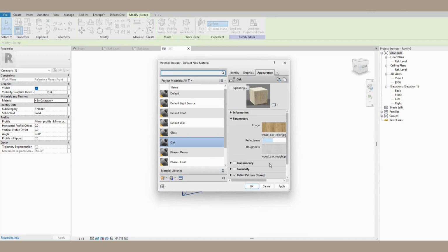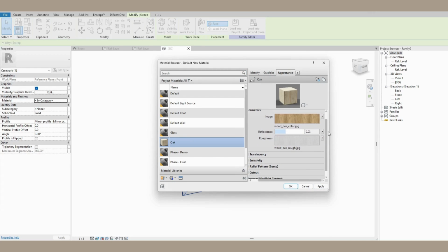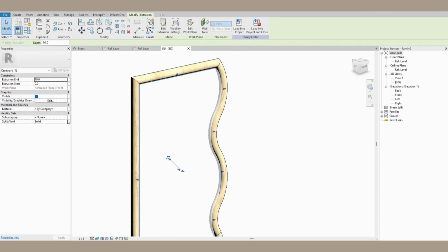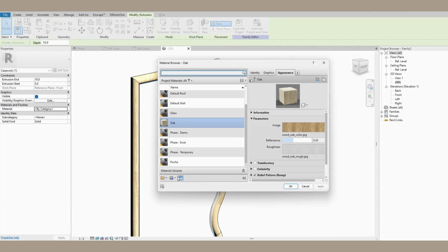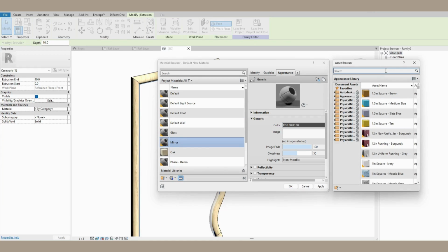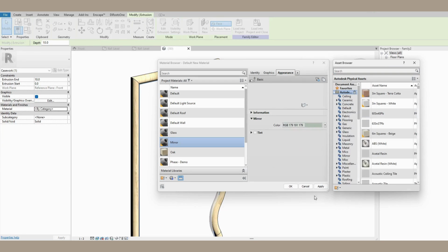And then we're going to add the mirror texture. So Revit has really good mirror materials. Create a new material, click the drop down in your asset browser, type in mirror. There will be a basic one or a chrome one. Let's go with basic for now. Okay, add it in. Fantastic. So as you can see, we've clicked the realistic view. Revit is trying to render your mirror, which is a bit distracting to see if the wood texture is there and how we want it. But we'll fix that just now.